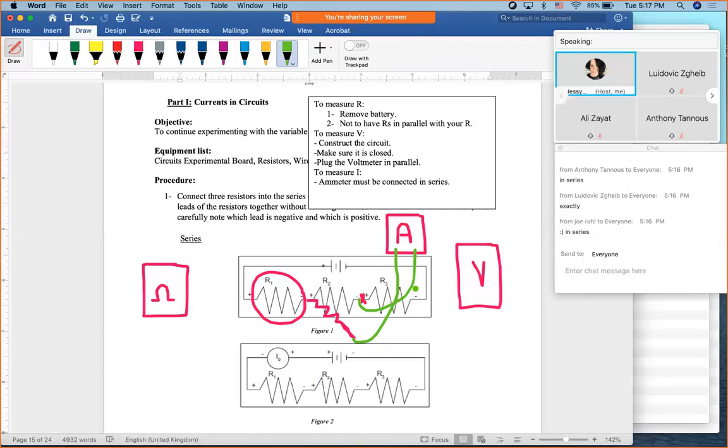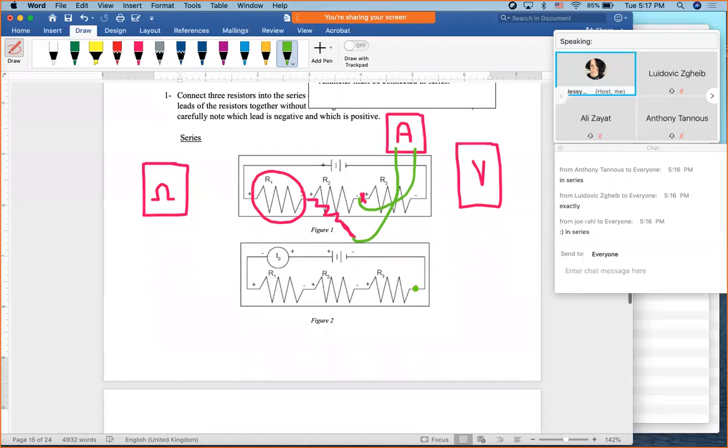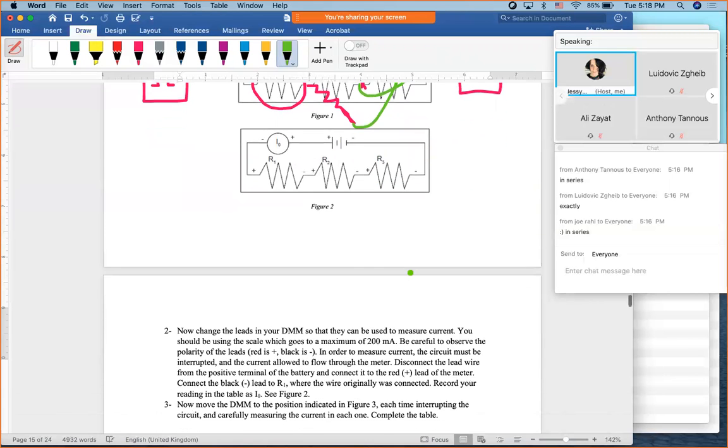All right, I know you will not struggle with this because you will be okay. I will give you the measurements. You will fill in a very simple table. You will measure the voltage of each, the current across each, and the resistance of each. You will be surprised to see that the current is the same. I know this is not a big surprise because you actually know this. And you will also be surprised to see that U1 plus U2 plus U3 is equal to U of the battery, obviously. And that's it for the first section.